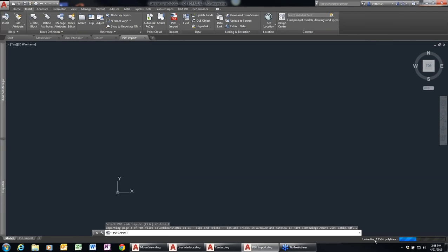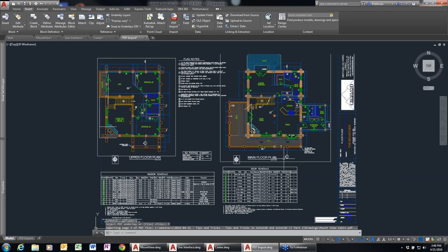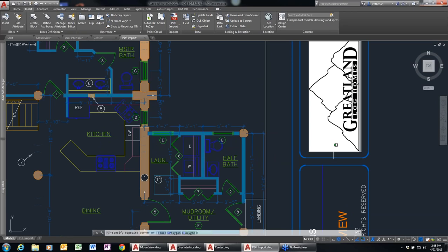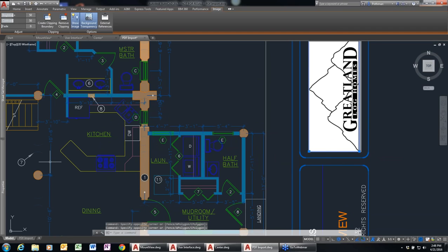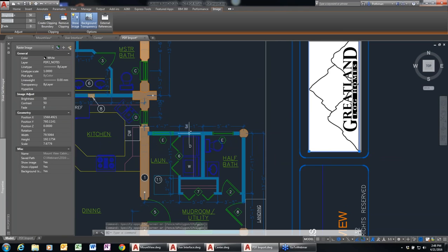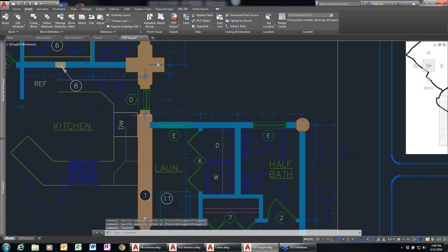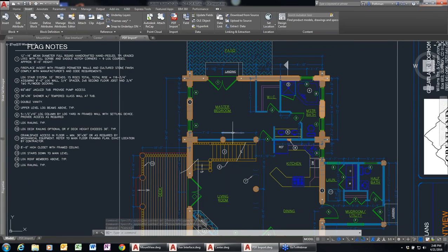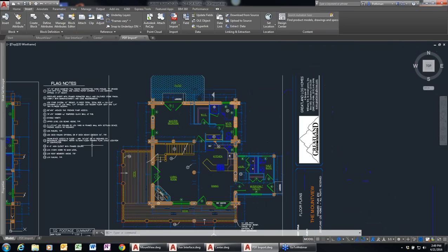And you'll see here it's processing 27,000 or whatever it was, different pieces of geometry. And here's my PDF file inserted now as AutoCAD geometry. So there's a couple things I want to show. First of all, how amazing is that you can convert something from a PDF file and automatically end up with the AutoCAD version of it, including, like I said, things like images. So let's see if I can grab this. That's the raster image that was inserted. We've got some solid fills here that were created, and this is not a dimension, but it's a bunch of text.